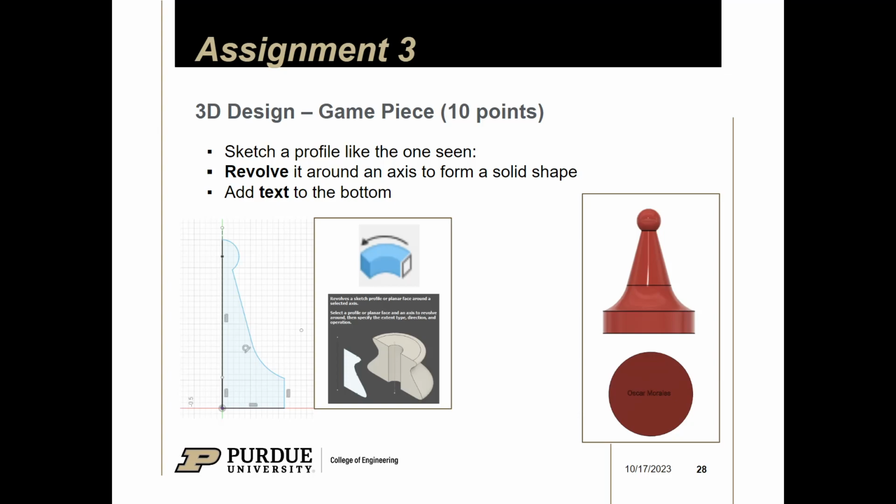So instead of extruding, we're going to be doing something called a revolve. It's basically going to take our sketch, and instead of extruding it in one direction, it's going to extrude it in a circle. You'll see in a second. Right now, our goal is to create a sketch kind of like this, and you see it's only half a chess piece. It's just a cut profile,